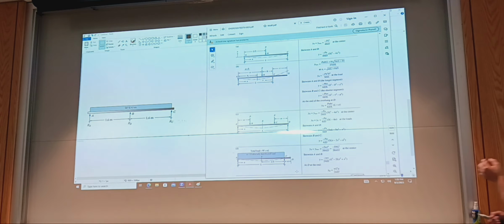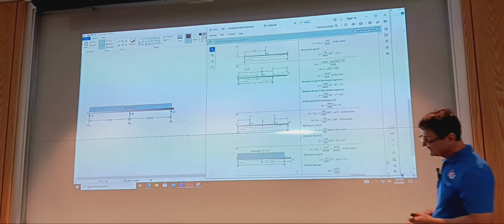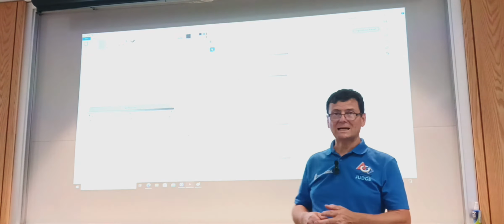You have a question? Yeah, I do. For the earlier problem, you mentioned this term statically indeterminate. Logically, it sounds like it's stable, but we're missing one or two variables. Okay, so what does it mean? This is statics. So what does it mean it's statically indeterminate? Using statics only, you cannot solve for the reactions of the supports, okay?